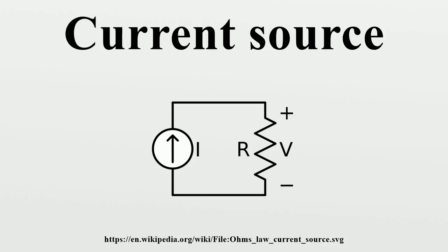This configuration is known as a constant current diode, as it behaves much like a dual to the constant voltage diode used in simple voltage sources. Due to the large variability in saturation current of JFETs, it is common to also include a source resistor, which allows the current to be tuned down to a desired value.